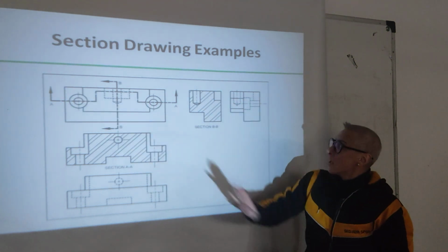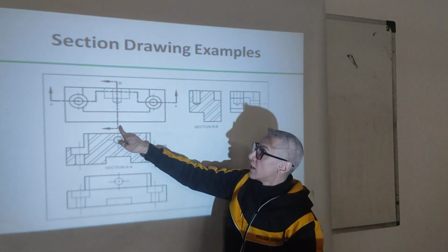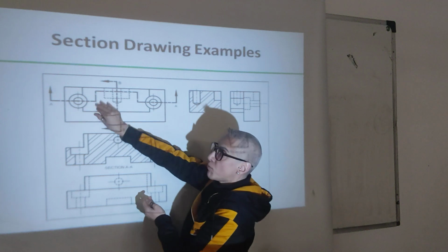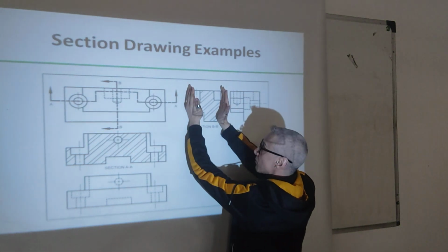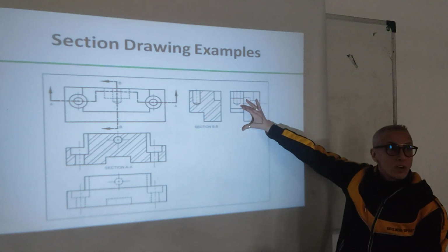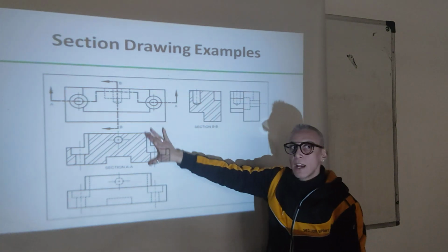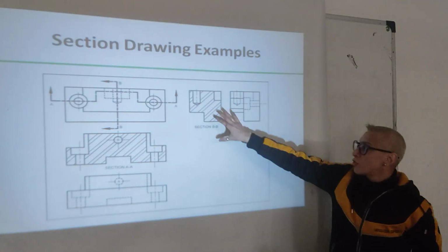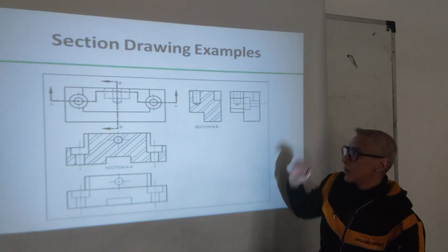Okay? Section BB is placed here because we have this line here cutting through. The arrows show in that direction. That means this piece is what we want. This piece is taken, rotated, and placed here, aligned. Okay? So, when it's possible to align the section views, you will put them in the correct location, not somewhere else, okay? So that we can understand what's going on better.